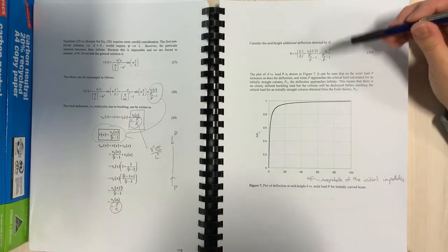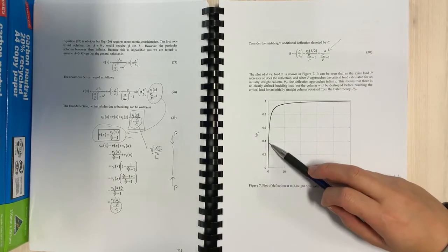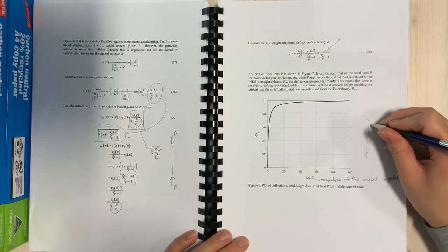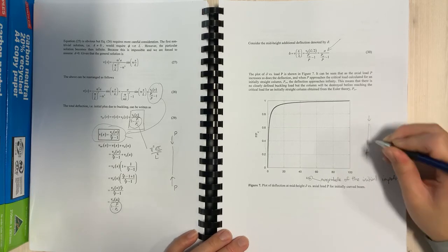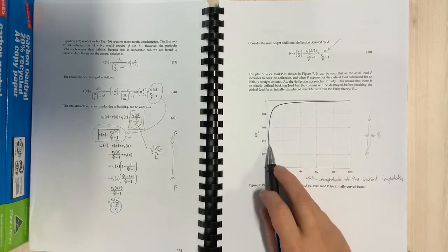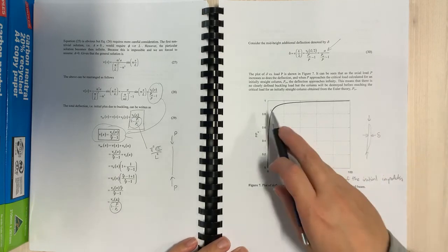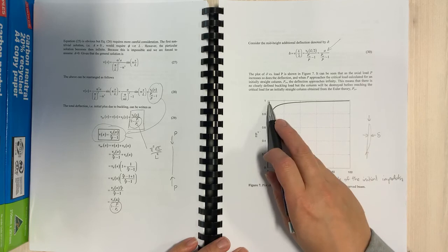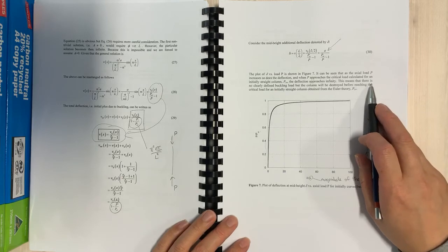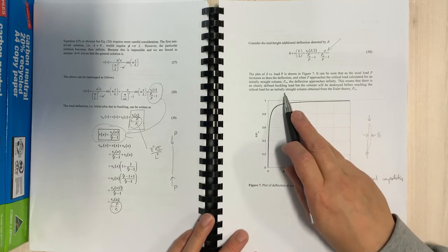So it can be seen that as the axial load P increases, so does the deflection. That would be that graph, and then that one here would be the delta at mid-height. As you increase your load, your deflection at mid-height increases, and when your load gets nearer and nearer to pi squared EI over L squared, you would expect your column to become unstable and it can't take any more load, and the column will be destroyed before reaching the critical load for the initially straight column.